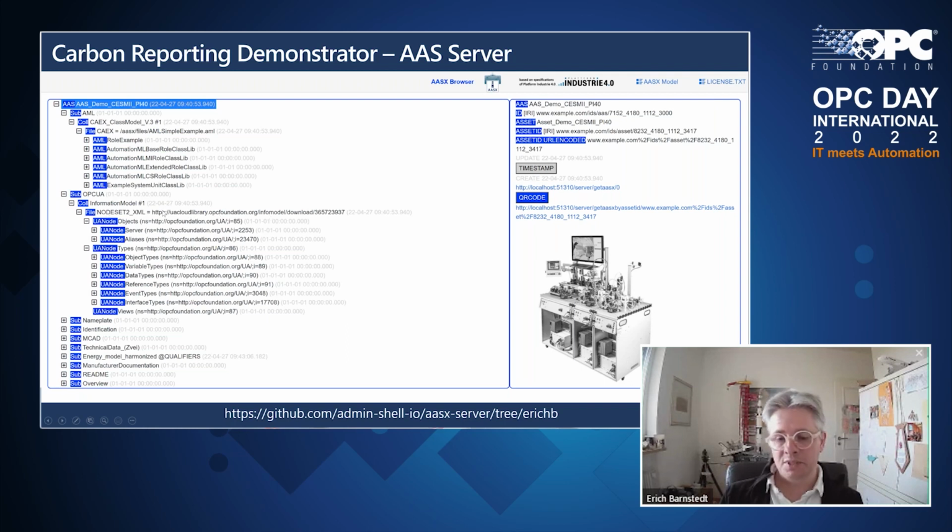And again, an OPC UA client and server was integrated, so you could parse the file. This is a nodeset file, as you can see, and directly browse the OPC UA information model within the asset admin shell. So this is how an integration should work and could work.